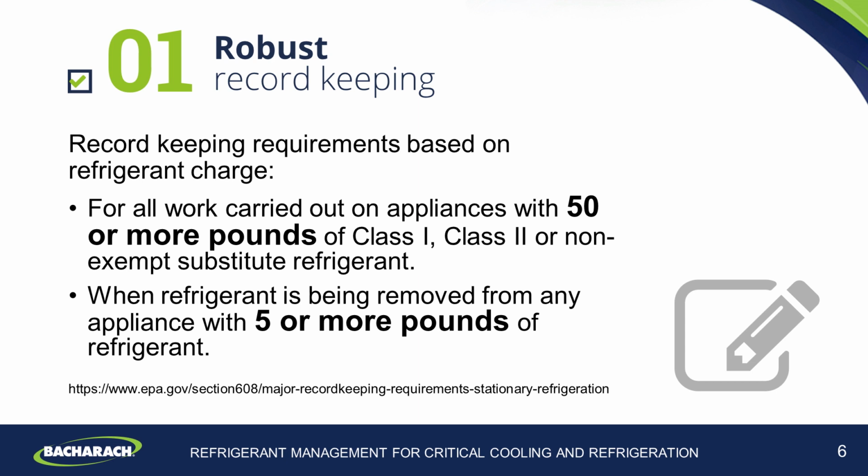Records are required whenever an appliance, a refrigeration circuit, is maintained, serviced, repaired, or disposed of. And that includes doing inspections, adding refrigerant, doing a repair on that appliance, as well as, of course, any retrofit or retirement activities.